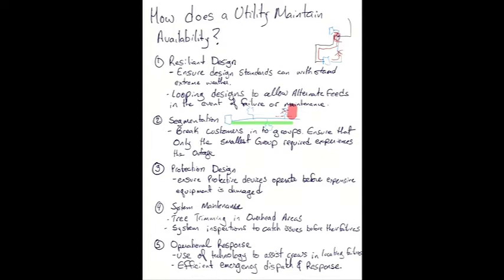We found the fault only occurred on the red phase. You can tell that to someone. Now they know if there's a blue phase section of line, there's no point paying attention to that. That's not where the problem was. You can save time in diagnosing the problem and get the power back on faster. Makes everybody happier.